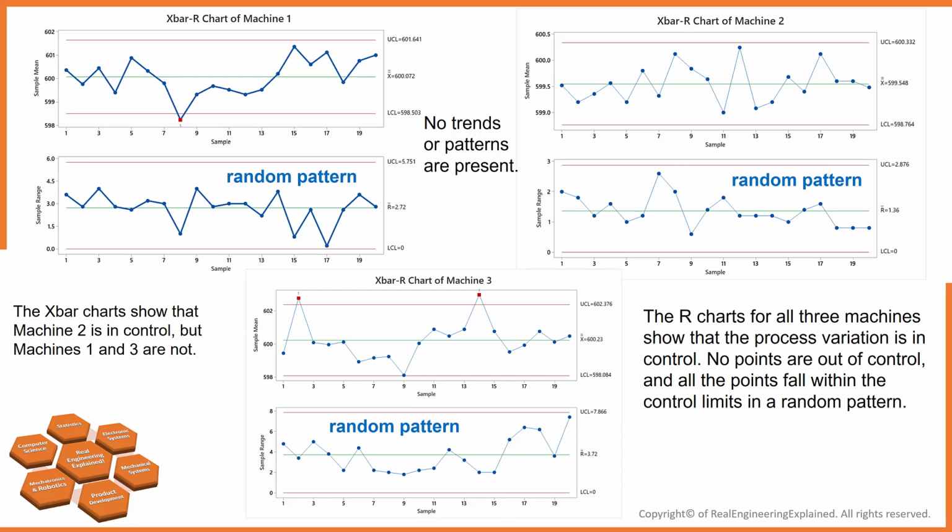By default, Minitab conducts only test 1, which detects points that fall outside of the control limits. However, if you conduct additional tests, then points can fail multiple tests. The output shows exactly which points failed each test.